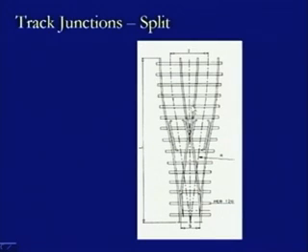And here, this is the center line of the main track, and this center line of the main track is produced like this, and therefore, at whatever angle it is taking a turn in this direction, the same angle is there at which it is taking a turn in this direction. And because it is symmetrical, we have only one point where the crossing is, and this is the V crossing being provided.